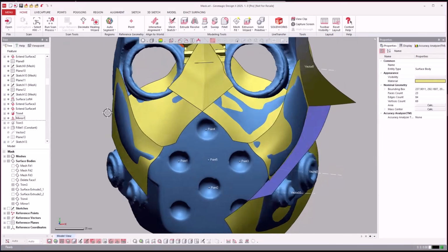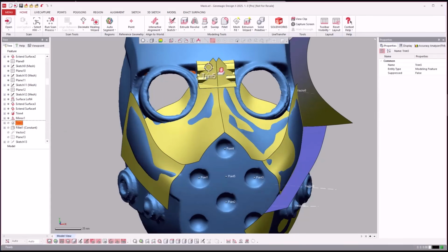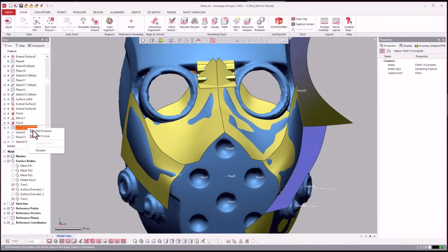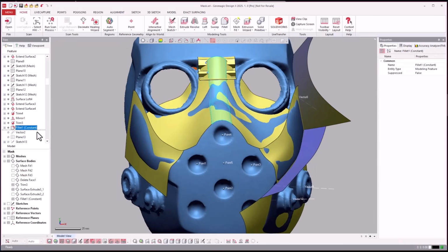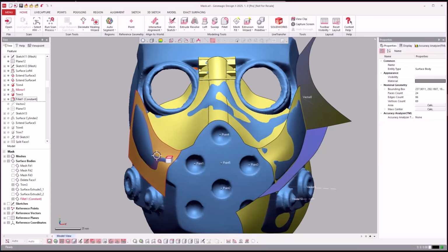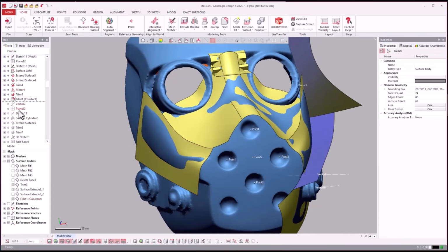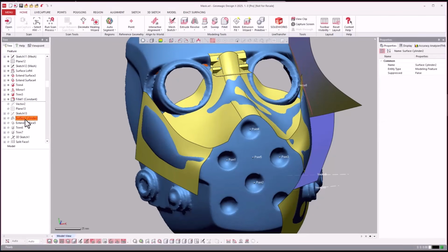We're going to mirror it across. Now, some people will say, hey, why don't you just mirror the thing at the end? I think they're mirroring this across right now just to be able to trim and find that center for this surface here, and then create that fillet. They're still going to mirror the final anyway at the end. And then you also can do this just to check and see how symmetrical this is as you go, just to say, is it very symmetrical? Do I want it to be, things like that.